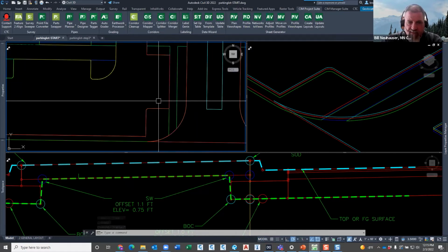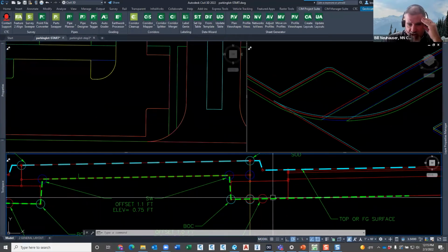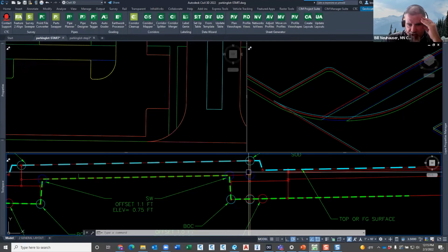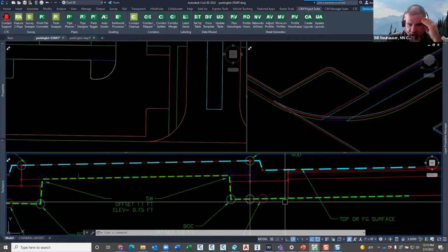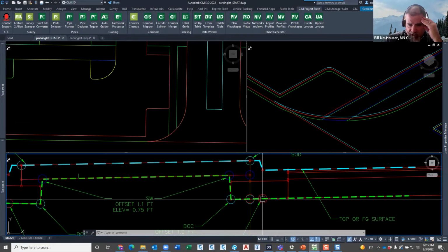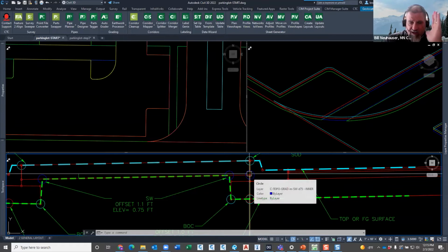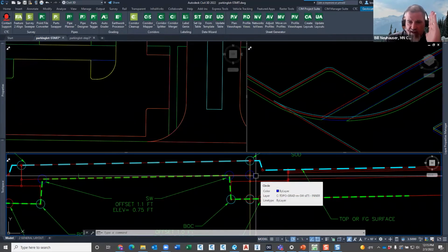Okay, now why is it important? The next step that we're going to talk about, where we start offsetting these, is because, for one, if I put all these in elevation, stacked them on top of each other, and then built my surfaces, the computer is going to have issues. We all know DTMs have a big time issue with a vertical face, a straight up and down wall, per se.